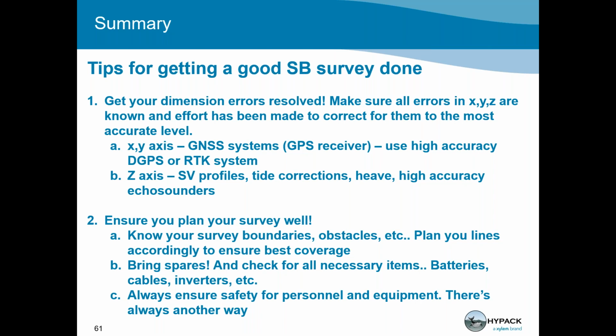Because I've had situations where we have surveys done in jungles, we've done surveys in the middle of mountains, and it might take 2 or 3 days to get to your survey area, and you don't want to abort the survey simply because you didn't bring a data cable, right? So it's important to check your spares, make sure you have 2 or 3 of each item if you can. Of course, for some items you can't because it's too expensive, but for cheap items you should have as many spares as possible. Also, last and most importantly, always ensure safety for personnel and equipment.